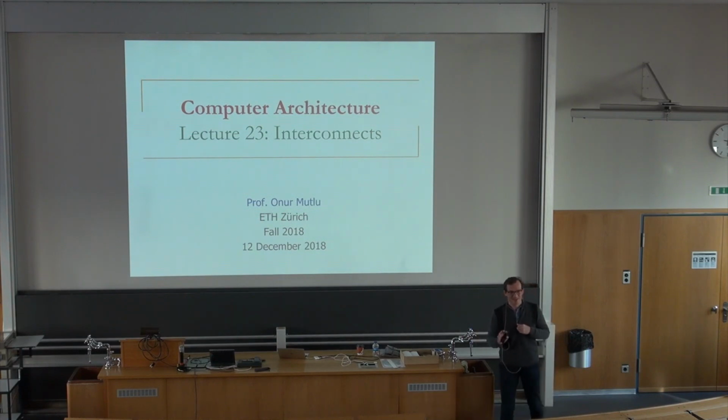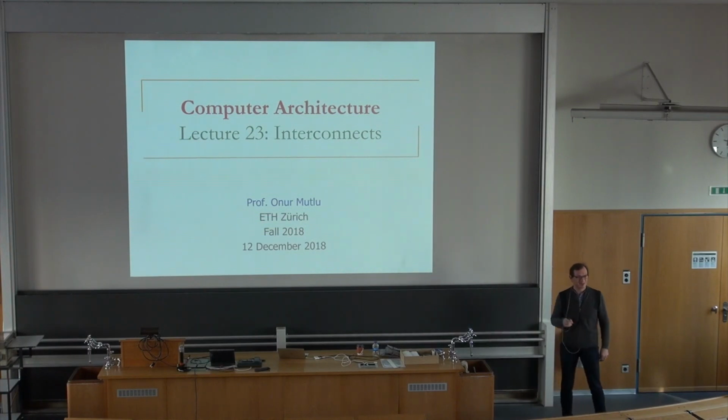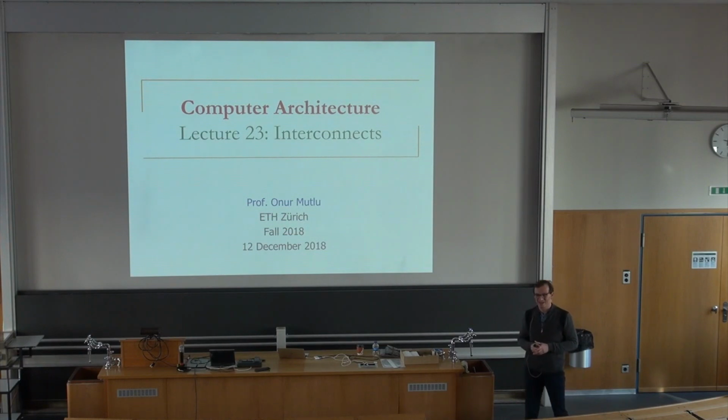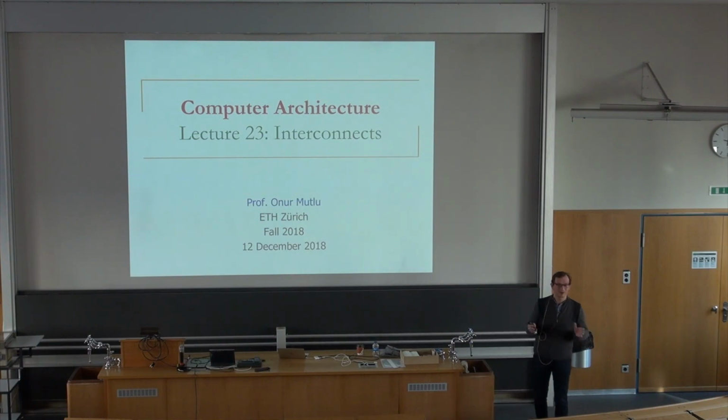And this lab exercise is just part of the difficulties in building a cache coherent system in real life. So if you actually go and design multi-core processors in real life, you'll have to design a protocol like this. And protocol is usually much more complicated than what you're going to design. And even the protocol that you're designing, the MESI protocol, is not simple to get working correctly in a real system because of the race conditions that you will see if you do the lab.